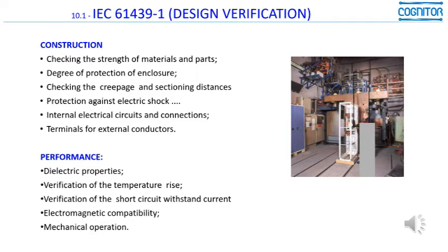Another important test, verification of short circuit withstand currents, where we will check if the equipment is able to support the very big force of short circuit. And here we are many times speaking about equipment where we will have short circuit currents in the order of magnitude of 65 kA, 100 kA, 8 kA, and of course all the forces involved in this kind of equipment are very severe, very strong, and this must be checked with attention.